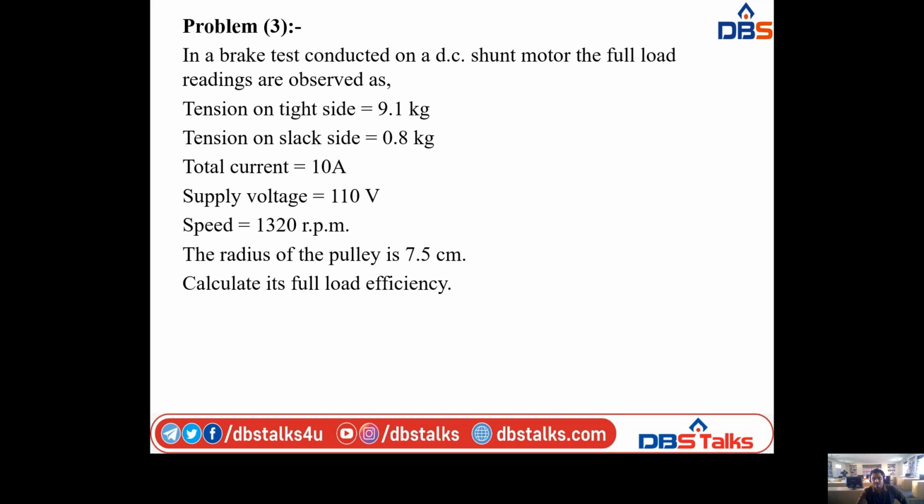And efficiency of generator, here also the output power of motor is given as input to the generator. So we already calculated that one. The output of the motor is the mechanical power and the input to the generator is the mechanical power. So we already calculated that mechanical power, that is generator input is equal to 7627.615 watts. And coming to the generator output power, we know the formula, that is input power minus total losses. So here the input power is 7627.615 minus total losses, that is copper loss plus stray losses. Here the copper loss is 481 watts plus stray loss is 430.615. And finally we have the generator output power, that is 6716 watts,